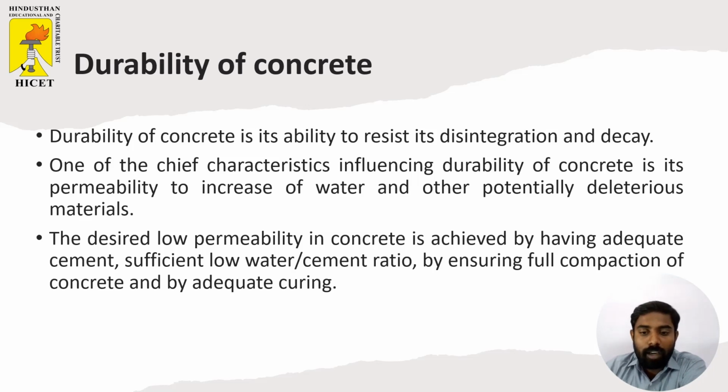The durability of the concrete is the ability to resist its disintegration and decay. One of the chief characteristics influencing the durability of the concrete is its permeability to the ingress of water and other potentially deleterious material, and the desired low permeability in concrete is achieved by having adequate cement, a sufficiently low water cement ratio, and by ensuring full compaction of the concrete and adequate curing.